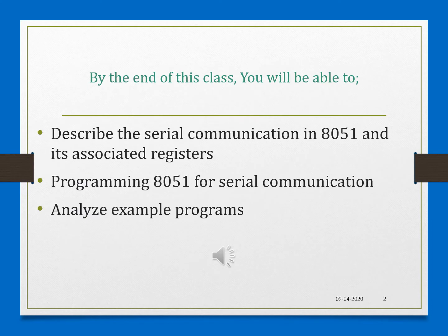Okay, in this session, we will discuss the serial communication registers of 8051 and show how to program them to transfer and receive data serially. The 8051 has a serial data communication circuit that uses a register called SBUF to hold the data. It uses register SCON to control the data communication, and register PCON controls data rates, and pins RxD and TxD to connect to the serial data network. We will discuss all of them in this session.